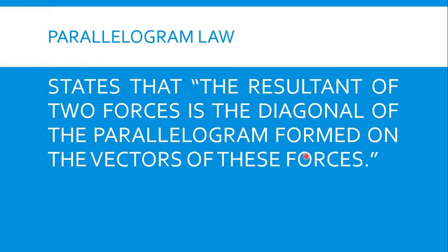So the parallelogram law states that the resultant of two forces is the diagonal of the parallelogram formed on the vectors of these forces, meaning to say that the two forces can form a parallelogram. Then the diagonal of the parallelogram gives the resultant of the two forces.